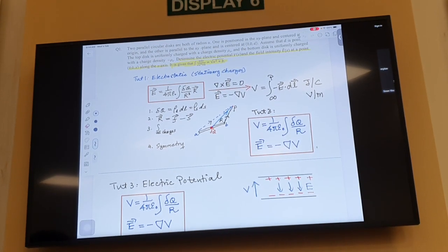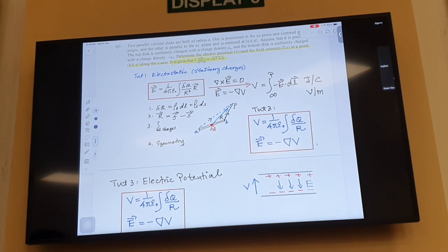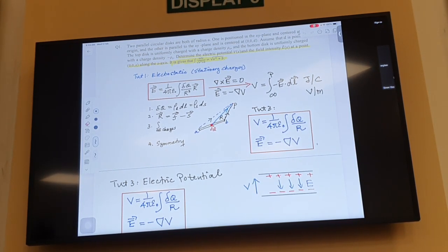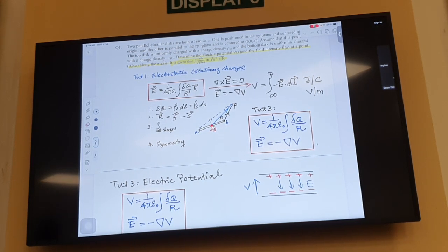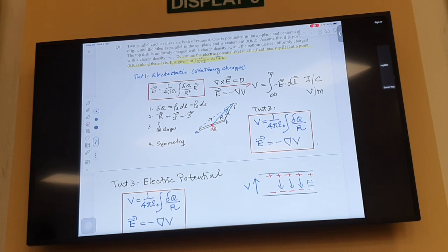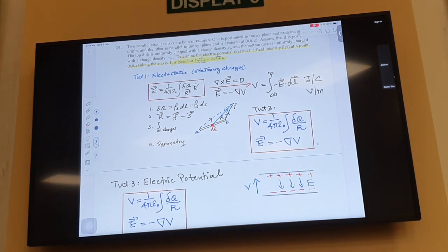Because electrostatic fields are stationary and irrotational, the path taken is not important. That is why you only need to define infinity, usually assumed to be 0 volt. Every point has a unique potential. This is only possible if you have an irrotational field. So you know that for an irrotational field, the integration is independent of the path taken. So if you choose 1 coulomb of charge, in joules per coulomb, you bring 1 coulomb of charge from far away, assuming the point at infinity is 0 potential.